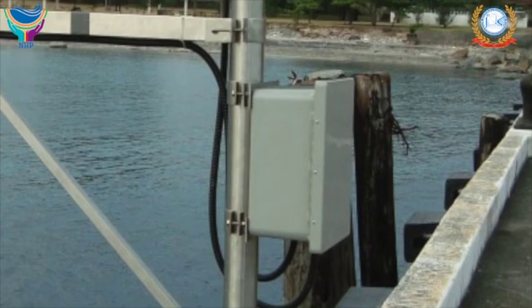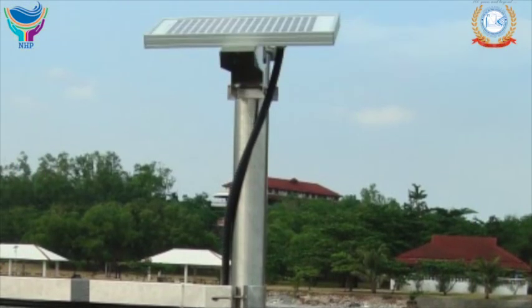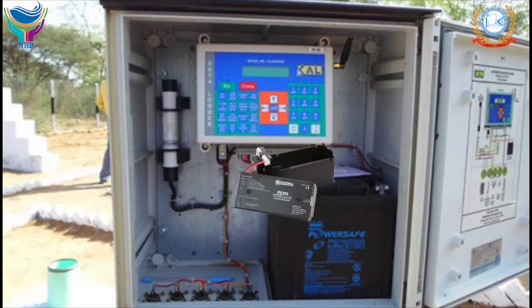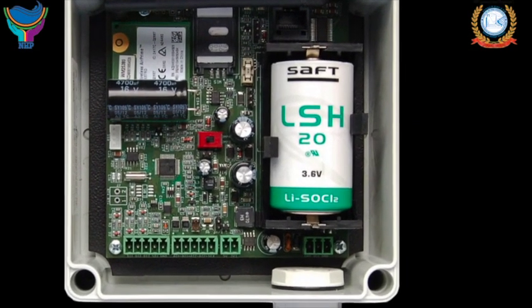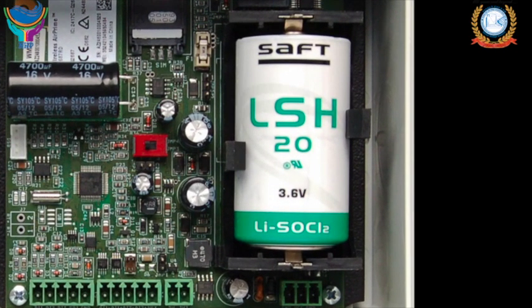The power supply and management system should be supplied to each station that has provision for charging batteries using solar panels. The system should use a charge regulator to maintain the charge of the battery and extend the life of the battery by not overcharging it. The battery should be sealed, maintenance-free, have a standard voltage rating, and be easily sourced and replaceable.